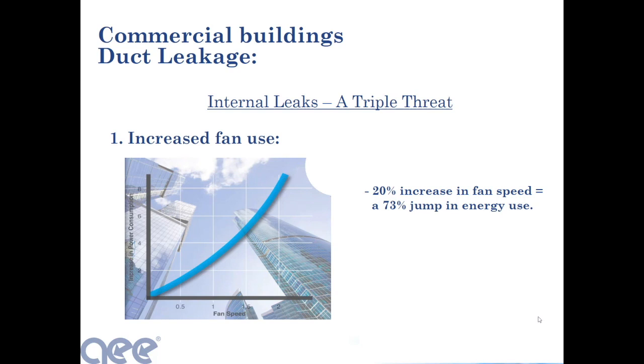It goes back to the fundamentals of engineering design. We know that whenever you want to double the flow of a fan, what do you do? You speed the fan up, right? The speed of the fan and the flow of the fan are proportional. We also remember that the speed of the fan and the power required to turn that fan go with the power of the cube. Think about that. If you're going to double the speed of the fan, the power increases by the cube.